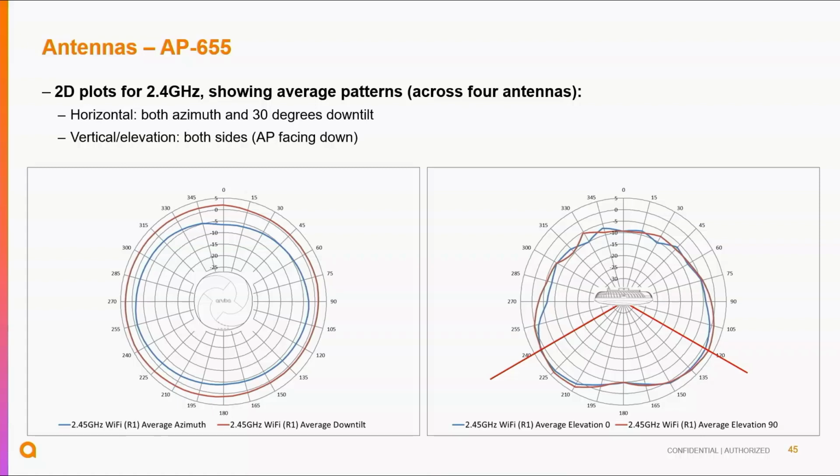So this is looking up at the AP, and this is looking at it from the side. Actually right underneath the AP, you typically have a little dip. In some cases, if this is an average pattern, that dip can go all the way. I've never been able to experiment with it, but theoretically, if you're standing right under the AP, you basically get no signal, because there could be a null sitting there. Okay.